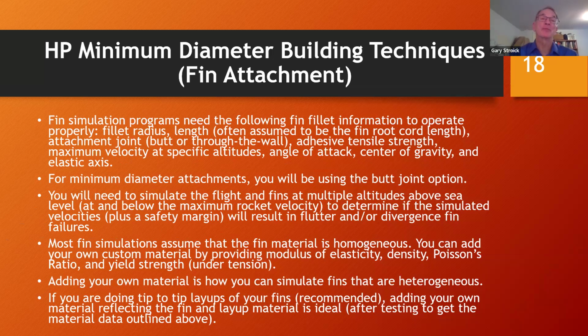So the adhesive is very important in terms of what's being used and how you actually apply that adhesive. You will probably end up wanting to rough up the airframe where those fins are going to be, so the adhesive has a good attachment point to the airframe, as well as the root chord of the fin. There's a variety of construction techniques associated with that, but the adhesive needs to be very strong.